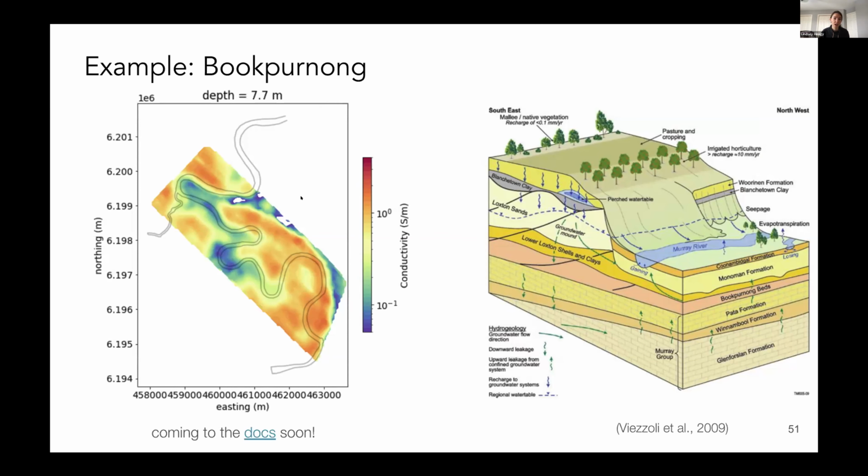If we get saline water coming from the irrigation region charging into the stream, that's called a gaining stream, and it can cause salinization because you have the saline water coming in. Another mechanism is if you have fresh water from the stream that's actually leaving and propagating into the groundwater system. And so that's reducing basically how much water is in the stream. So that can be another mechanism for it becoming more saline.